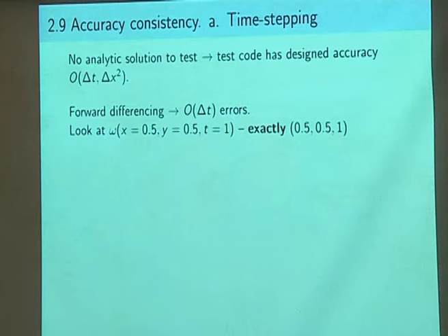And I want to plot something, so I'm going to plot the vorticity in the middle at time equals 1. And I'm going to compare with different calculations, so I have to be very careful that I am exactly at the middle and exactly at time equals 1. Comparing time equals 1 and 1 plus delta t is going to be delta t different. So I have to be very careful. So that's why I have to make my delta t's 1 upon an integer in size.